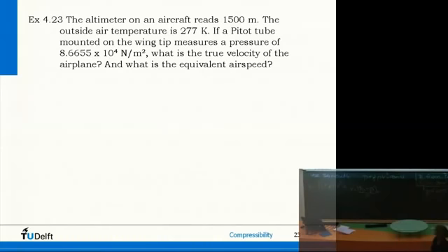Equation of state. Yes, very good point, because the temperature is given, right? So you might be tempted to look in Appendix A for the density as well, but we have more information here. So the more actual information you have, you should use it. And why is the temperature given here? Temperature is much easier to measure. How do you measure densities? It's very hard, but temperatures are always monitored, so always measured. So the temperature is given, so we find rho from the equation of state.